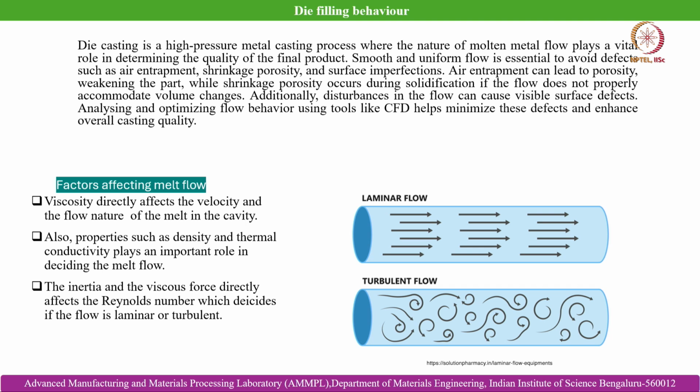Whereas shrinkage porosity occurs due to improper feeding of the solidification shrinkage, because of lack of proper gating design and proper risering design, so that the melt is needed to compensate for the density change, which is the higher density of the solid compared to the liquid state, the primary reason for the shrinkage that takes place. So improper feeding of the solidification shrinkage causes defects in the cast part and weakens its structural integrity in a big way.